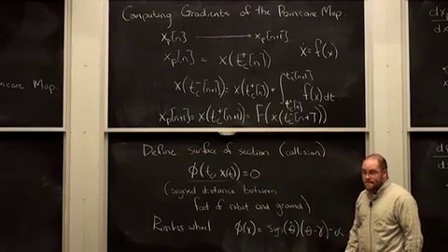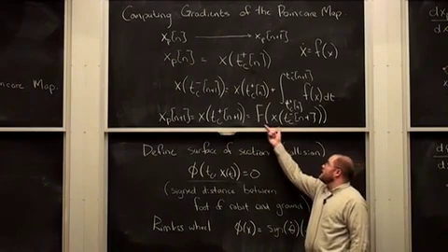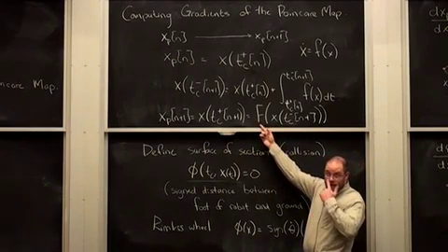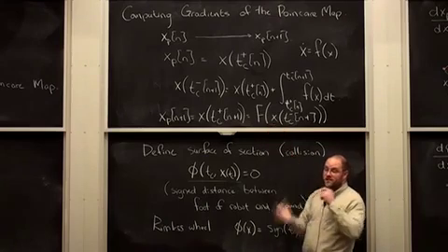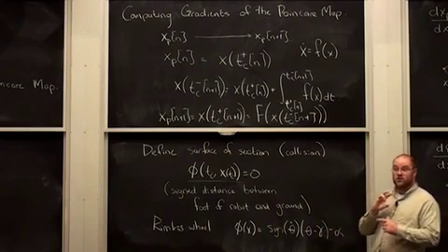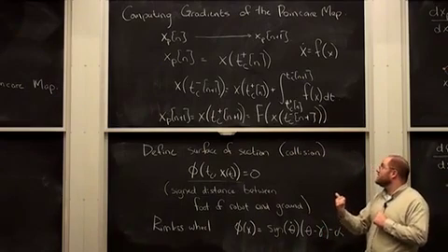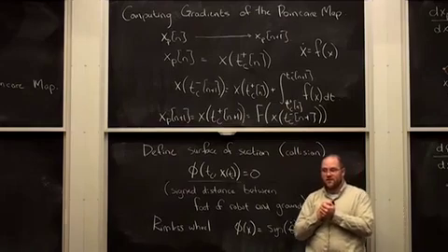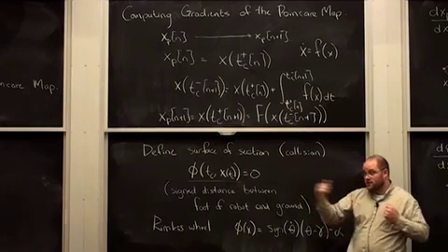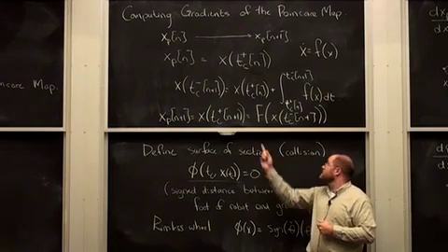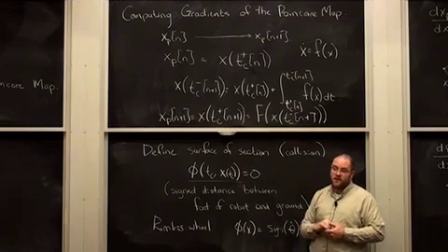This is the equation which says, in the rimless wheel example, I'm going to change coordinate systems back to where my new leg is on the ground. So I'm actually going to do a discrete change in theta, and I'm going to take away some of the theta dot because I've lost some energy into the ground, right? And in general, when you have collisions in mechanical systems, if you model them as impulses, you're going to have some function like F.